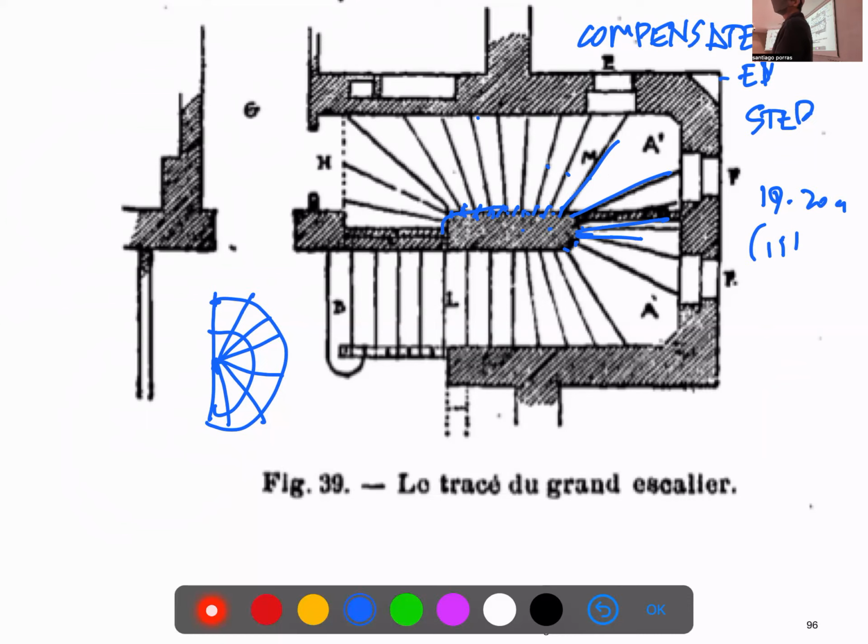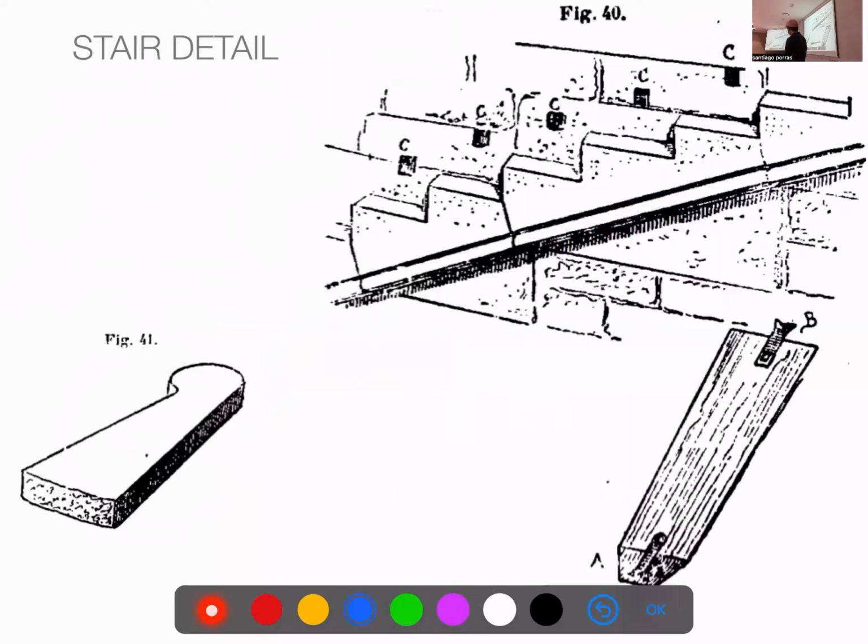Again, traditional schools used a lot of time on those things. Now we expect the software to do it for us, but I don't know of any intelligent software that's able to do that properly. But it's an interesting thing in this part, right? You see how they start compensating the steps much before the corner. That makes a much safer, much more comfortable stair to climb. One interesting detail for steps: cantilever steps, if you have the space for that.